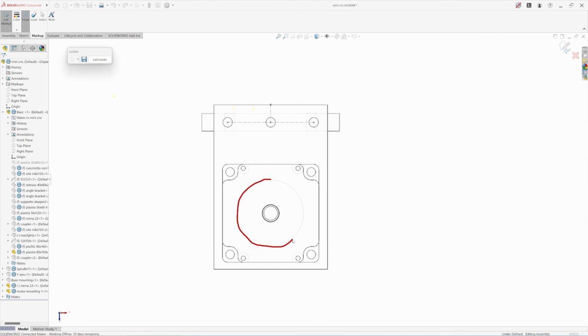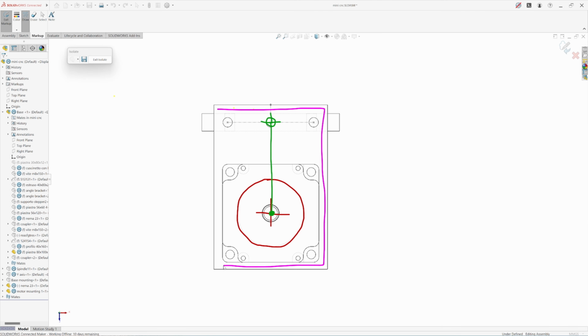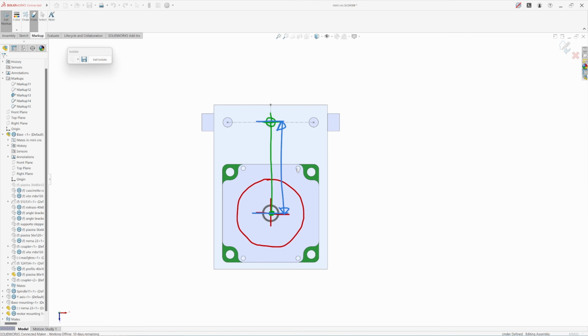And I would like to maintain the motor step guide hole position with respect to these mounting holes, rather than from any side, top, bottom, or the middle. So even if the overall size of the part deviates, increases or decreases within the allowable tolerance limit, of course, the motor position will remain the same with respect to the plate mounting holes, which is necessary as per the assembly. I will show you its practical as well. And this is also a design intent, the positional design intent of this motor guide hole.